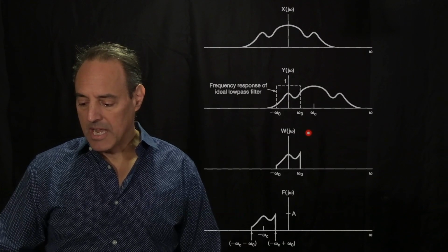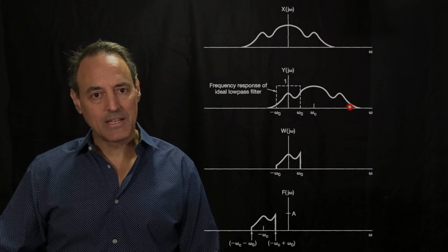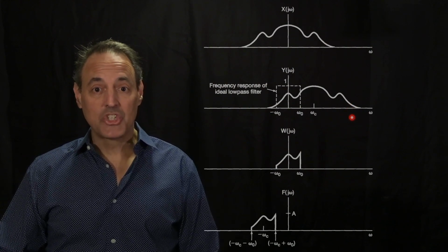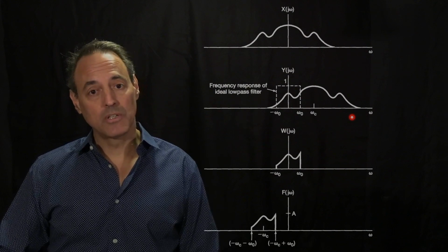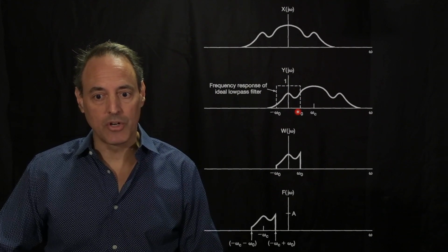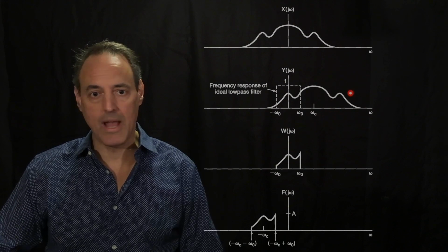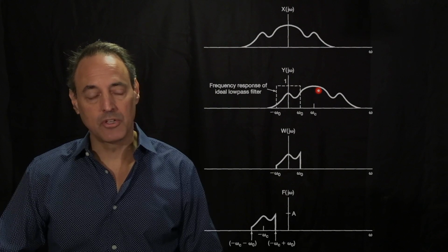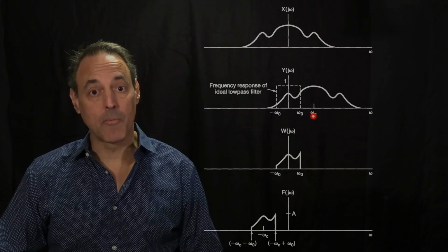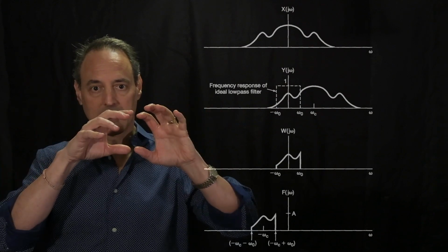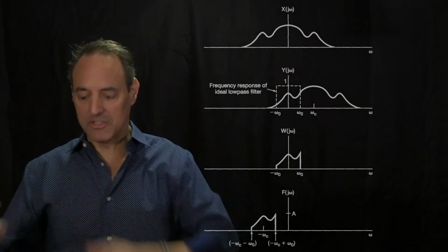Okay? And what ends up happening is that signal, remember that e to the i omega c shifts it. It corresponds to shifting this thing. So now you took this whole thing, you shifted it over here. Okay? That was just what happened when you modulated the signal. It took this thing from here, shifted it over, and it shifted over by some omega c. Okay? So you brought this thing in, you modulated the signal, now its Fourier domain gets shifted over.